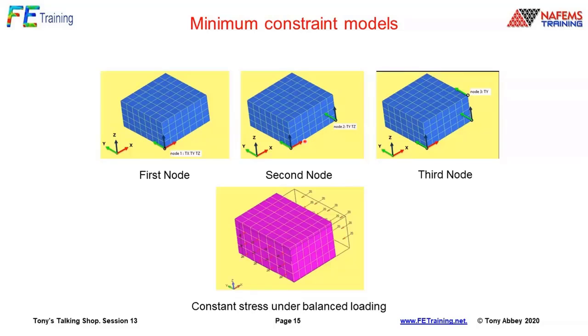So I have one last constraint to apply, which is again we shoot off here at right angles and constrain that in the y direction. That stops that last spin about the red axis. So that's 3 constraints, 2 constraints, 1 constraint, hence the term 3-2-1. That's the minimum set of constraints. We've got 6 rigid body modes, we applied 6 constraints, so then we're in business.